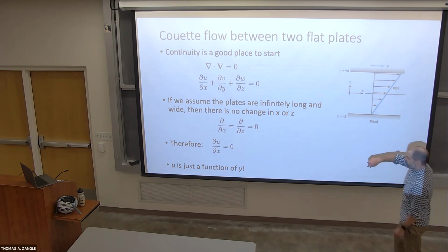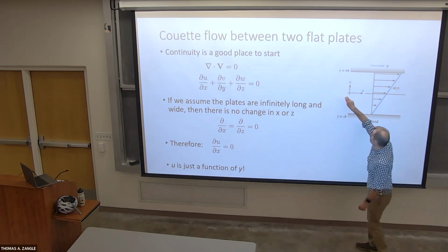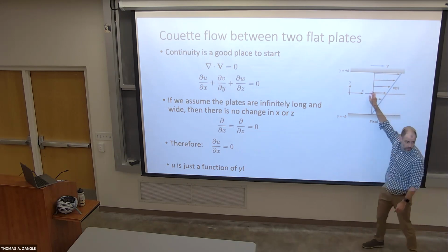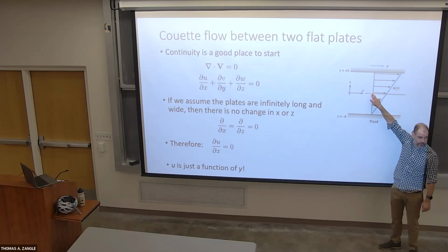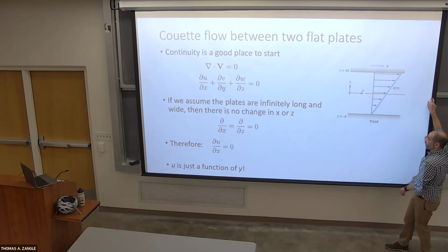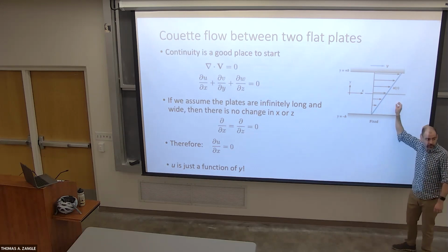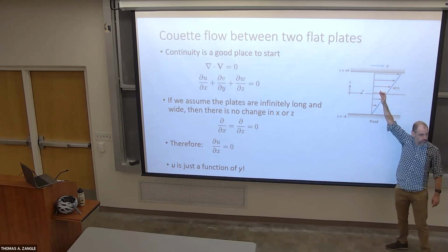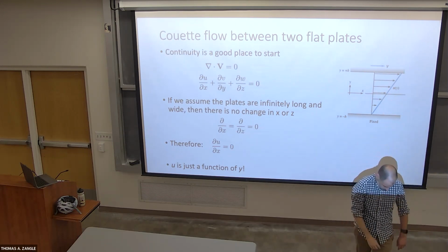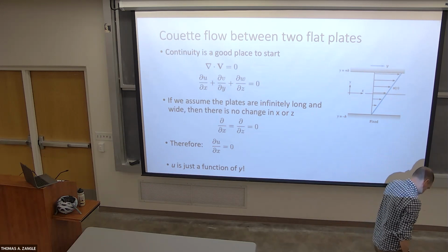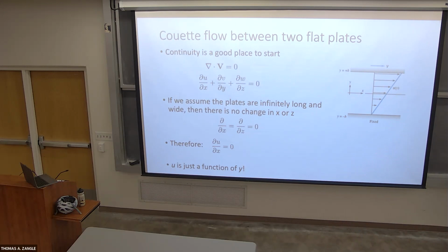So yes, this condition implies that along some horizontal line, we're looking at the center line here, the x component of velocity u is the same everywhere along this. It doesn't vary in x; it only varies in y. But the dy is not equal to 0. We could have a situation where it goes up a little bit, or it could go up a lot more, where the velocity changes linearly, but it's in y.